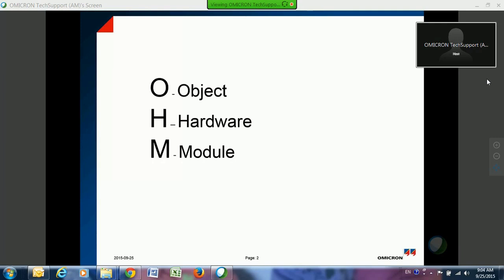The second part is hardware. Hardware is very important because you need to configure your test set to be able to use the proper currents that you want to be using. It allows you to set up whether you're going to do 3 or 6 individual currents, or you can combine currents together to get different values, from 75 amps max to 128 amps if you're using a CMC 356.